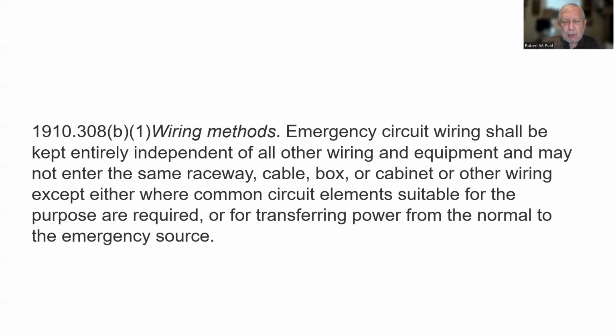Wiring methods. Emergency circuit wiring shall be kept entirely independent of all other wiring and equipment and may not enter the same raceway, cable, box, or cabinet, or other wiring except either where common circuit elements suitable for the purpose are required, or for transferring power from the normal to the emergency source. So that's some.